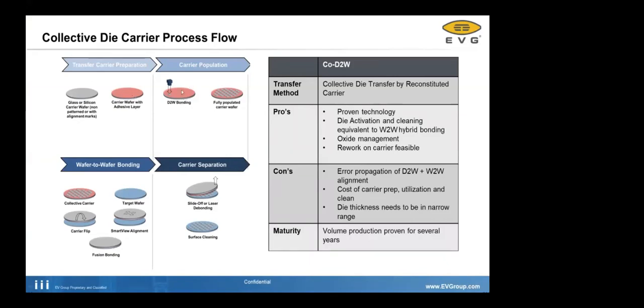So we can do this in an aligned way, where a die-to-wafer bonder of a third party, in this case, it's not EVG. EVG's core technology to build die-to-wafer bonders is aligning the dies on top of the wafer and then attaching them to the adhesive. So we are not doing any permanent bond, we are just lightly placing them on top of the adhesive.